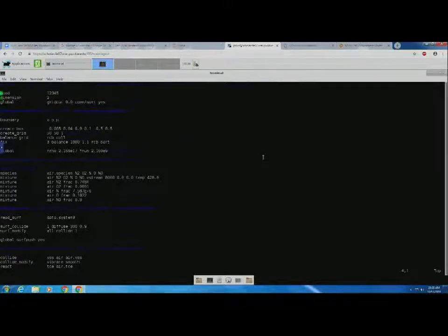First, the dimension of the problem is either 2 or 3. If you have a 1D problem, then usually you just make it 2 and set your boundary conditions such that the problem is 1D. The grid doesn't really change between 2D and 3D. That's one nice thing about SPARTA: it still keeps a 3-dimensional grid. If you have a 2D problem, you just make one cell in the Z direction and make the boundary conditions appropriate.